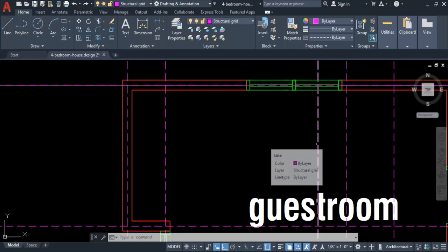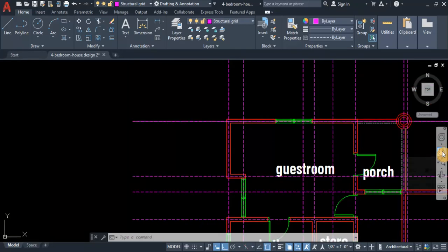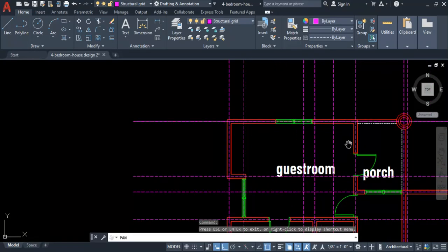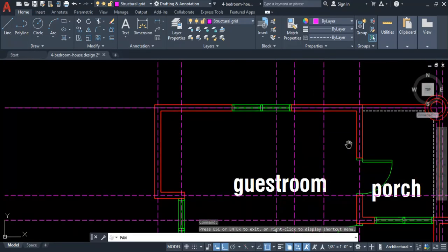But in this case, the architect is going with a 6 inches wall without even considering the structural aspect, because normally when placing our columns on the wall, we like the columns to flush with the wall, so that the columns are not projecting outside of the wall, because this will not be good aesthetically. So the architect just decided to go with 6 inches wall without even considering the structural aspect.